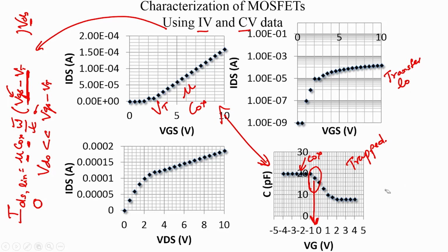At the high frequency characteristics here, we know that this is a series combination of Cox and the semiconductor capacitance, and that is basically the capacitance here, which is 10 picofarad, divided by the area, and let us say it is a 100 micron by 100 micron device. So, this divided by 1e minus 8 is nothing but the series combination of Cox and Cs.